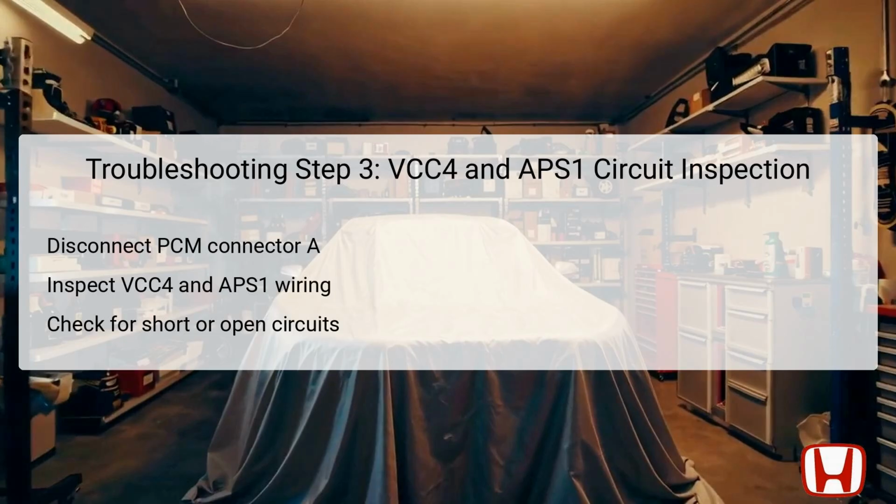Next, inspect the wiring for the VCC4 and APS1 circuits for any signs of damage, shorts, or open circuits. A normal inspection will show resistance values of less than 1 ohm. If any anomalies are detected during this inspection, you will need to address them to ensure proper voltage flow to the APP sensor and subsequently the PCM.